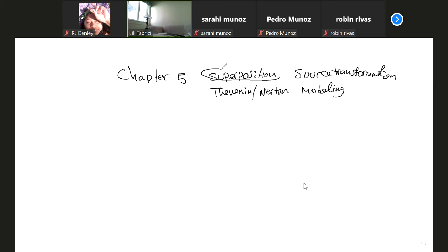Okay, so far we covered superposition. I also assigned a homework problem for next Tuesday to practice superposition and source transformation. Both of them are kind of short methods, not too many guidelines: just keep one source at a time, kill the other sources, go through circuit analysis, find the quantity, and add them up. Do you have any question about anything before I start? Any question about any topic, any material, any problem?